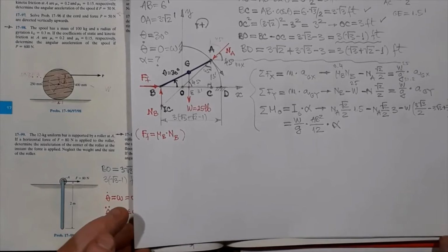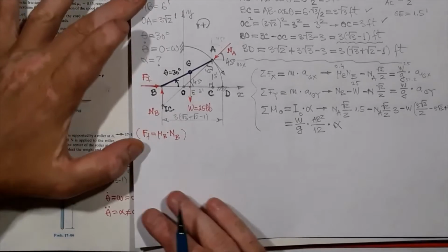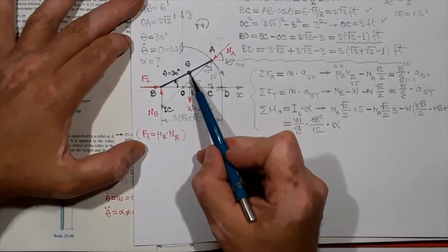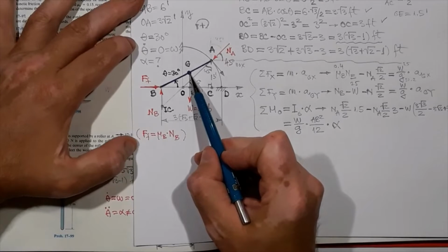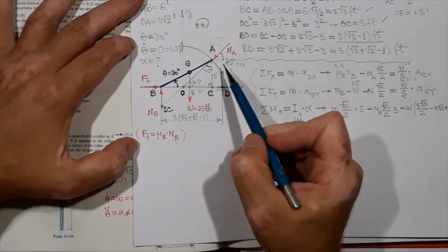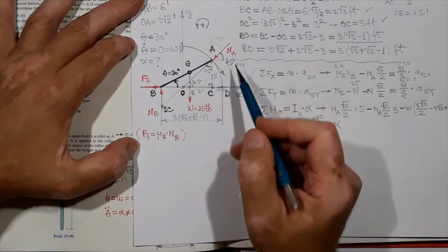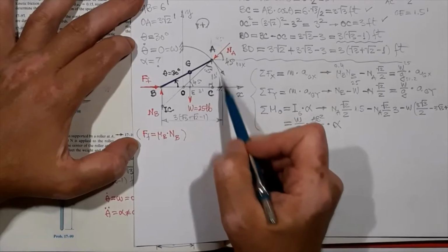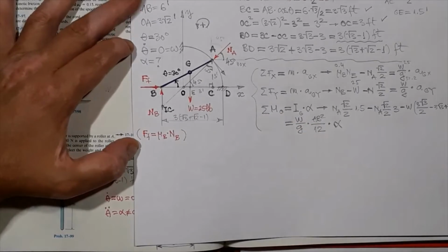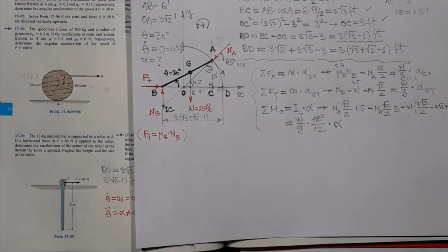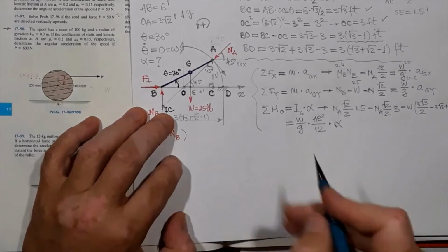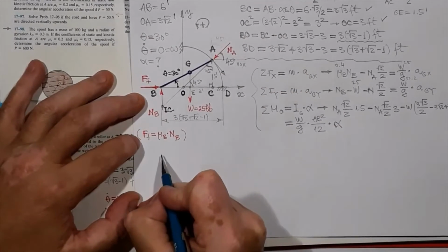Okay, and that will come from kinematics. That means it's a matter of relating alpha to the acceleration in the x and y direction of the center of mass, and we need to make use of the fact that point A is moving on a circle, and point B is moving on a horizontal line. The way of doing it is to state the relative acceleration equation, vector form.